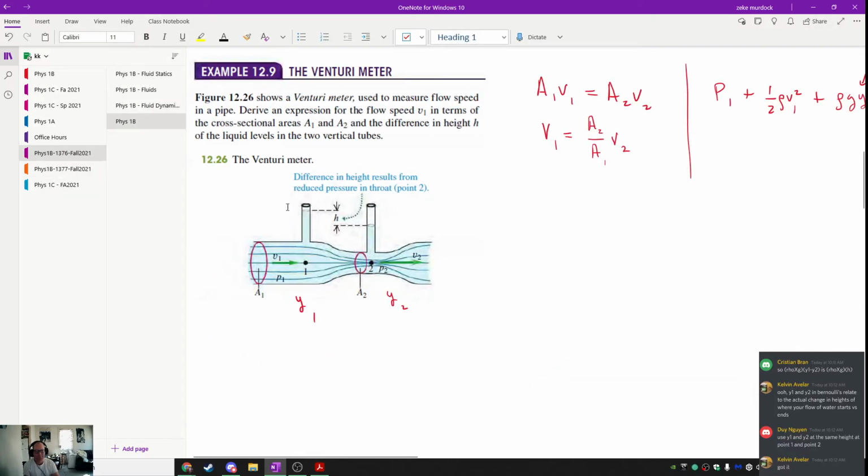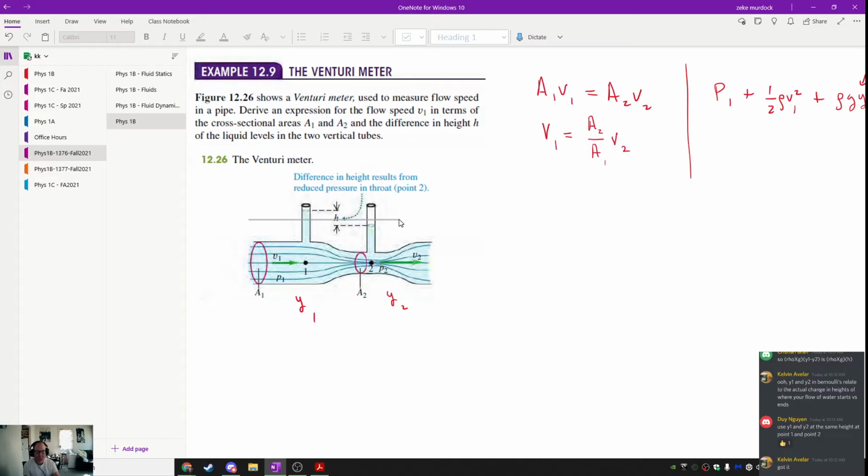It's very tricky. It is very tricky. It seems like you should use this, right? But the reality is that the fluid is flowing through here. And what's happening in these pipes above the fluid, I believe this is correct, is a result of the flow of the fluid, right? So I started this off by asking the question, what would the pipes look like if there was no fluid flowing? And you all answered correctly that they would both be at the same level. It'd be somewhere in between, right? They'd both be at a level somewhere right here, right?